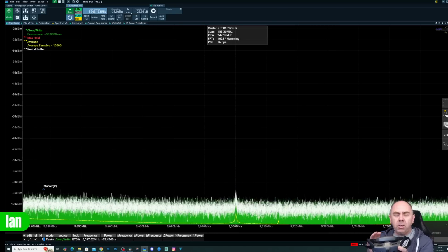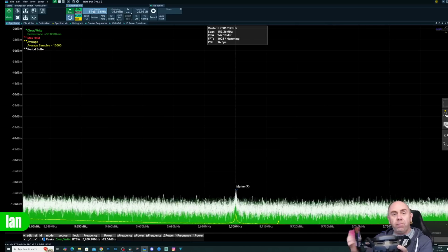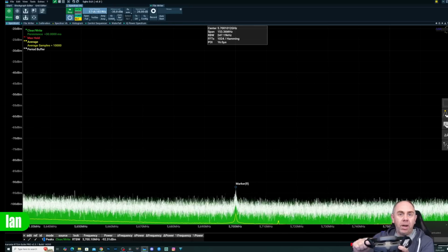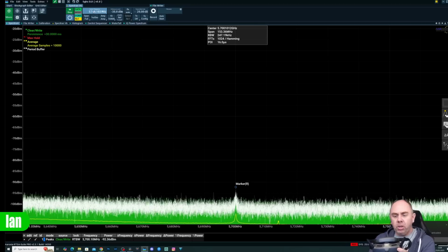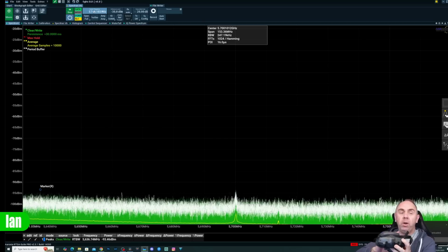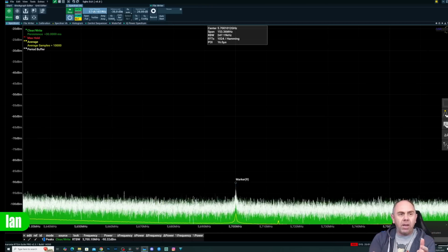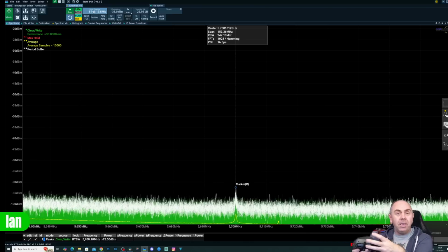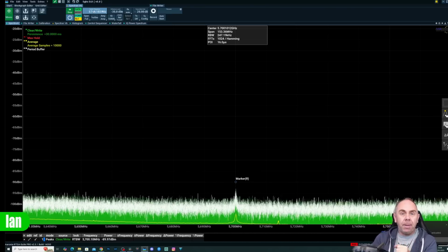About the only thing to watch is I have seen there's a bit of a quick band scan when you first power the ear unit up and it connects, but as I have said already, it will connect and it will jump straight onto the last channel used. But with regards to walking around with these goggles powered on, there should be no issues at all. What you wouldn't want to do is put them right up against someone else, because there's always going to be some form of EMI, but overall from an RF transmission perspective, they're basically dead.